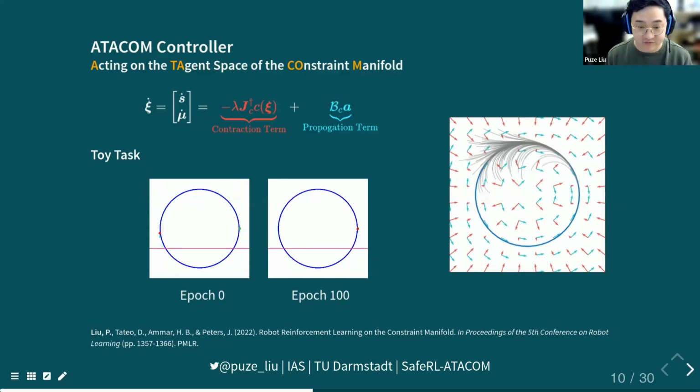For example, in this SDF model, we define the margin to be 3 or 5 centimeters. I don't remember completely, but this margin to avoid collisions is sufficient in our scenarios, and we don't really have any collisions during training or during real world deployment.